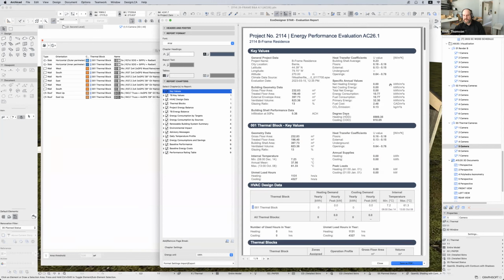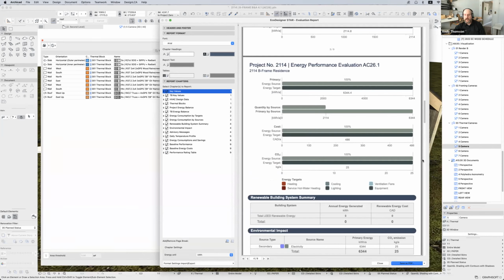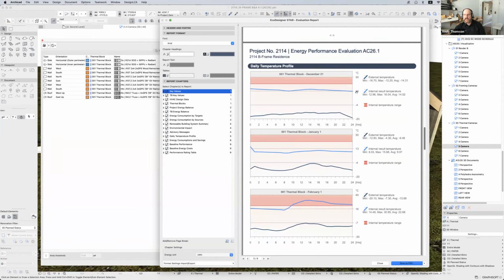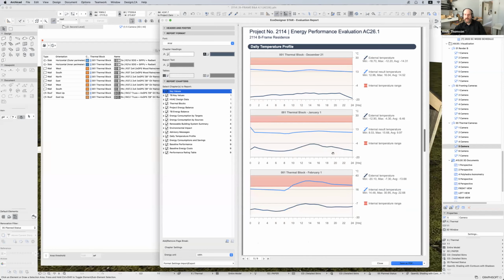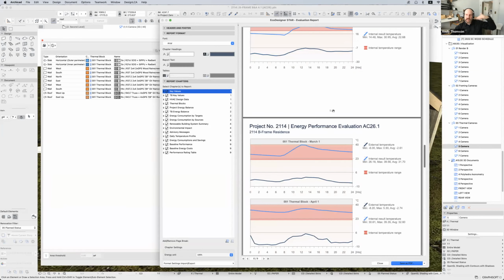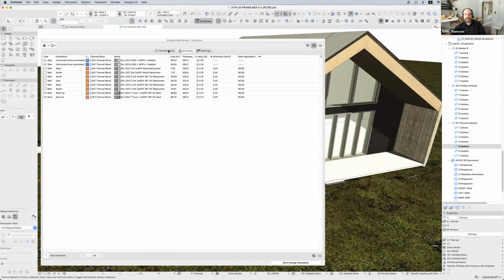Now, when I add energy systems to this, I'm going to get better performance. But right here in the winter, I will probably start to see that just based on tightening up the air leakage, I'm getting a better indoor temperature. Now I'm above 10, I'm at 13 in December, right? So I'm seeing that I'm getting that heating season number line higher without doing anything but changing the envelope characteristics, right? If I add more insulation, it'll get better and better. So let's get out of here, and I'm going to start adding systems to the building.